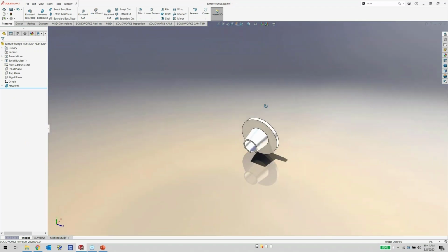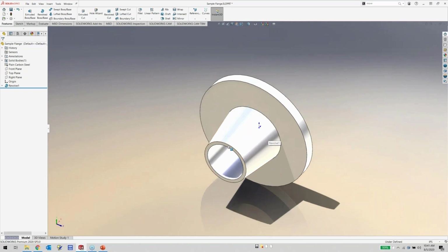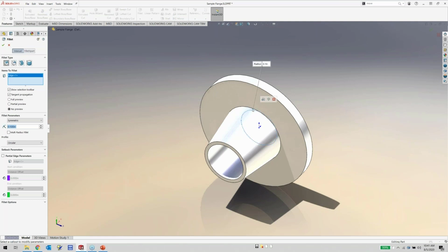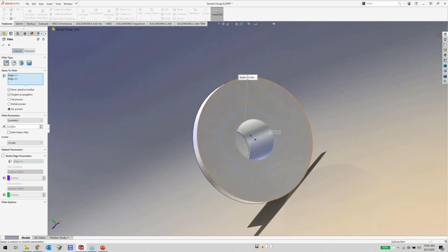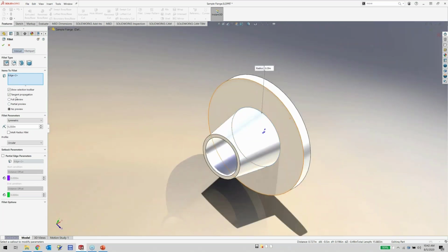So now I have what would be similar to a weld neck flange and those sorts of things. And I have this, and I've drawn up and I've put bunches of features. I've put fillets. I've put other things in it. In fact, let's just drop a quick fillet on there so you can see there's more than one feature. Let's use that edge and maybe this edge. We'll go ahead and put on a 0.25 fillet. Got one. That looks pretty good, so we'll make sure that we can see that. That looks good in the preview.